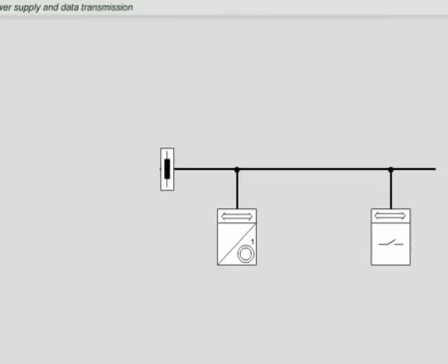During specification, the EIB was defined so that the bus could operate with only a single wire pair. This wire pair has two functions. It supplies a DC voltage of 28 volts to the bus devices. At the same time, data can be transmitted over this wire pair. The telegrams are modulated on the DC voltage.